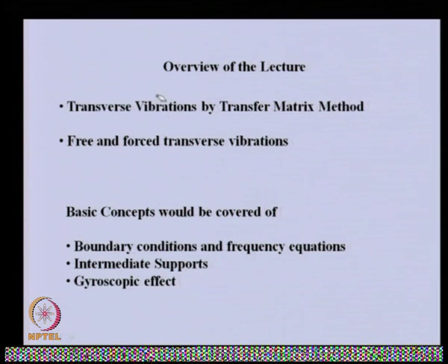So, again we are dealing with the transverse vibration, TMM method, free and forced vibration we will be covering, and basic concepts would be similar to the previous one. Some of the things like boundary condition, frequency equation. Now, this frequency equation, especially when we consider gyroscopic effect, we will see that the natural frequency will depend upon the speed of the rotor itself. So, as such, the form of the equation, whatever the frequency equations will be there, that will have more complexity.